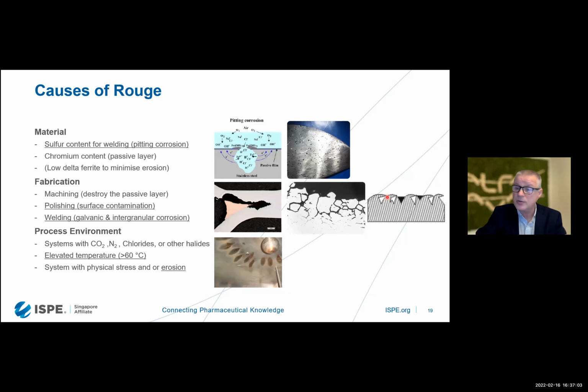And when you have a lot of residues, because they are small particles, they generate a huge surface area, and these cannot be passivated. So you have a huge amount of ferrite with a large surface which cannot be passivated. So if you don't remove these polishing residues, you will definitely get problems with rouging in the system. And that's why we can see in many tests that electropolishing is preferred, because then you remove all these polishing residues from the system.